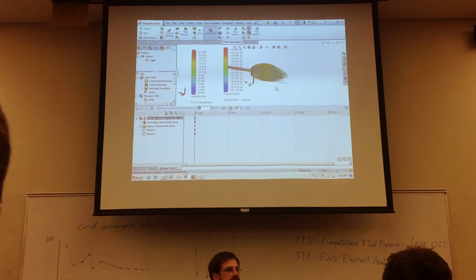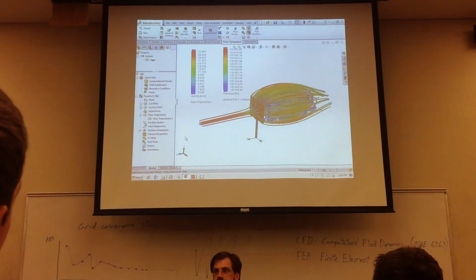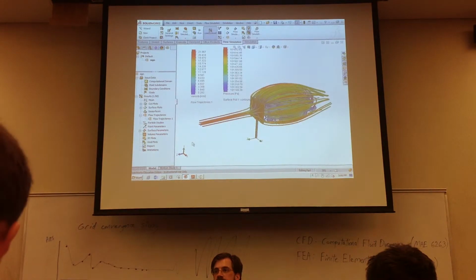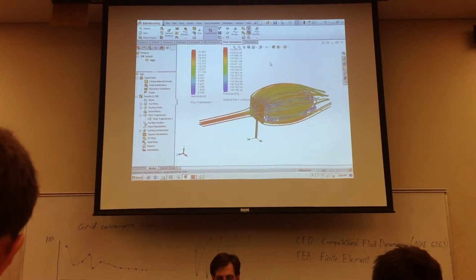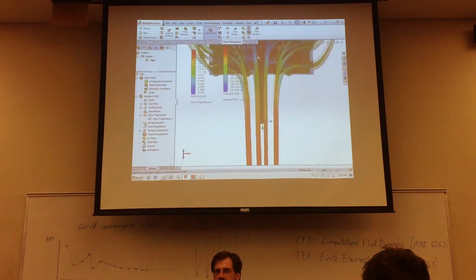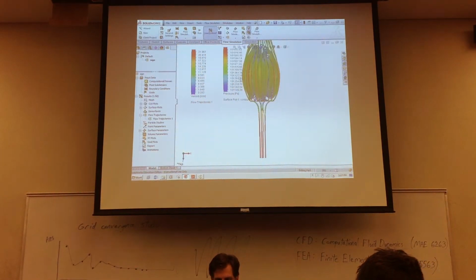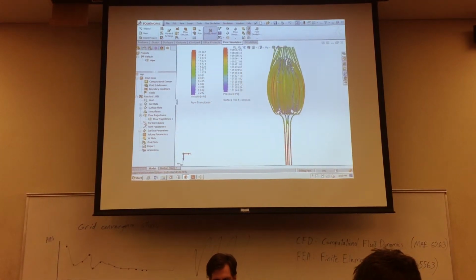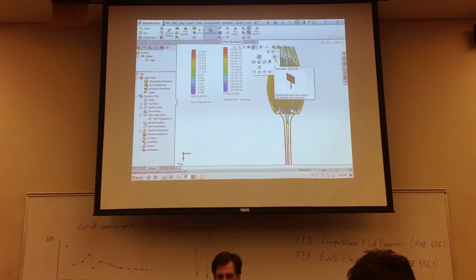Okay, any other questions? He also mentioned during lecture to ask you about dimetric view. Okay, so the different view types or view orientations, like you're used to using this button up here to get your front view, your top view, and stuff like that. Well, in that same button, right over here is where you would get an isometric view, but if you click the drop down, this is where you can get a dimetric and a trimetric view.